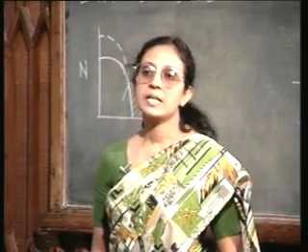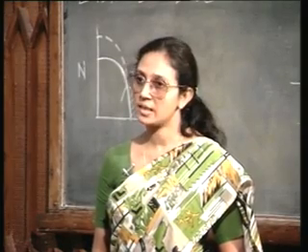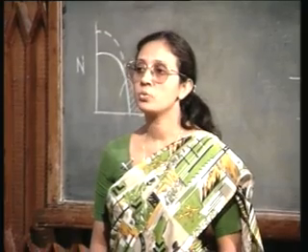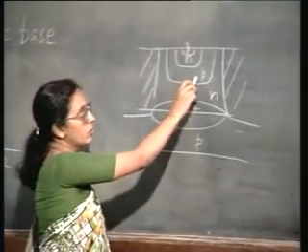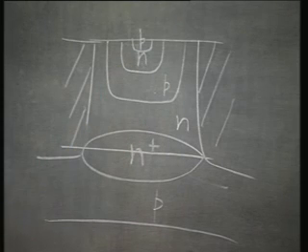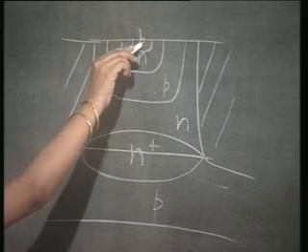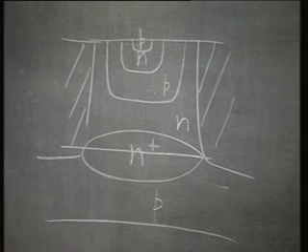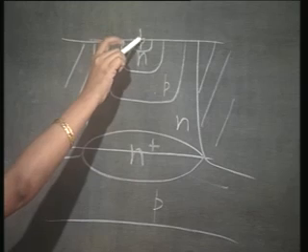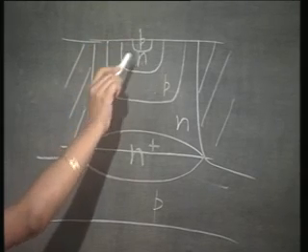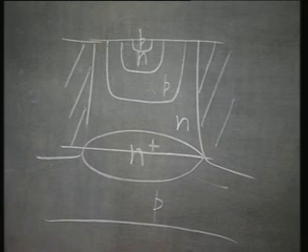You see, realizing an NPN transistor by double diffusion process itself is quite tricky, because you are going to use two subsequent diffusions, one after another. One for the base of the NPN transistor, the other for the emitter of the NPN transistor. Now, the process we are talking about is a 3 diffusion process. You have another P diffusion, and remember that diffusion means this is the highest surface concentration, then this, then this, then this. So, it is going to be extremely difficult to realize a PNP transistor by this 3 successive diffusion process. So, even though this is a possible solution, this is not really feasible.